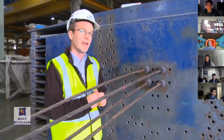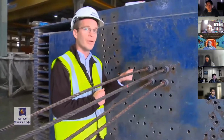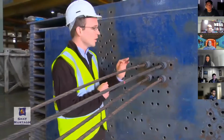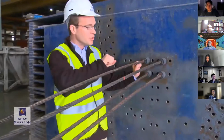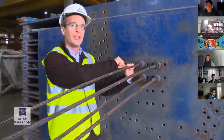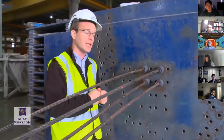This particular strand, in fact, we would tension up to a load of 209 kilonewtons in just one strand. So these strands would be jacked up, pulled back, and essentially stretched. They would be put into that very large amount of tension, 209 kilonewtons for these.